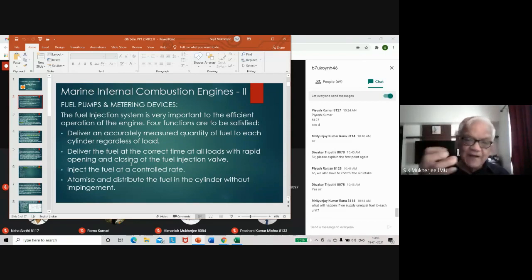The amount of combustion taking place in the engine will determine the exhaust gas temperature leaving the unit. If you burn less fuel, then the heat generation will be less, and the temperature will also be less. So one look at the dial gauge, which will show low temperature, will be directly indicative that this unit is not developing enough power.